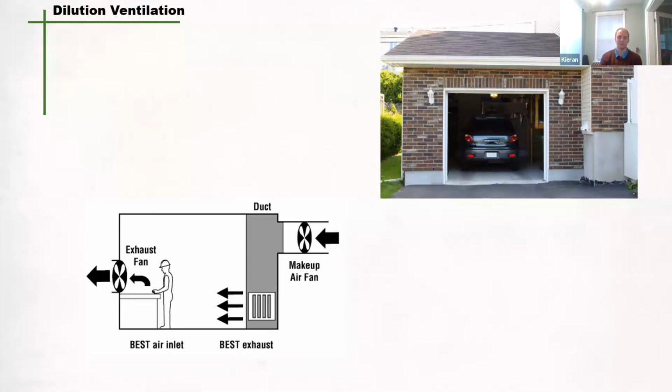The emissions are mainly vapors or gases or respirable size aerosols. When you say respirable, it's less than 5 micrometers, which can then be sent into the alveoli region of your lungs, which is not good. If you want more information on respiratory hazards, check out some of our other respiratory presentations. To get back on track here, removing heat from an area by flushing outdoor air is another use. If machines bring a lot of heat when they turn on, this is a good way of getting rid of it.